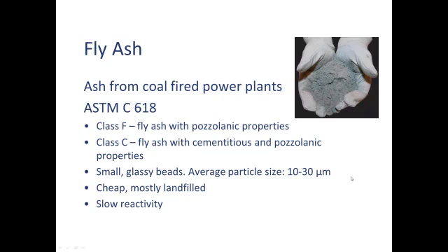One of the benefits of using fly ash is because these are small glassy beads, they look like tiny ball bearings, it adds a lot of workability to the concrete. You can make very flowable concrete. The reason why it's not used in concrete countertops is because it's a completely non-refined product. One source might be the color you see in the picture, another source might be black. Next year when you get it might be a different color. So you have no control over your colors or the shade of your colors, and you lose a lot of early strength. The reactivity is very slow. So you might not even start to see a recovered strength for a month or so. Well, that's too long. It's fine for the construction world, but not fine for us.